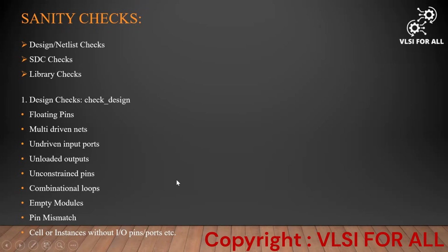ports, etc. The cells are what we call instances. So they should have some pins or ports. If a cell does not have any IO pins or ports and is not connected, that is also one of the issues in the design checks. So these are all the checks which we do in the design category, or the netlist checks.